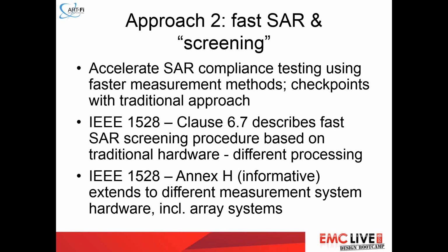So the idea is if you have a faster SAR measurement system or tool or procedure, you can apply it and basically measure all the conditions. So in this case, you don't reduce. And in the end, you will end up with a group of test conditions that give higher SAR. And you can reproduce those conditions with legacy systems to ensure the data you measured are solid, basically.